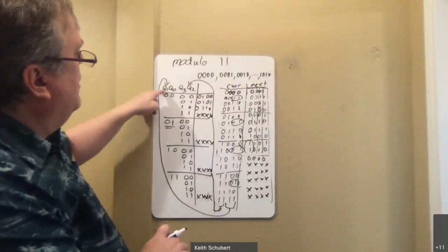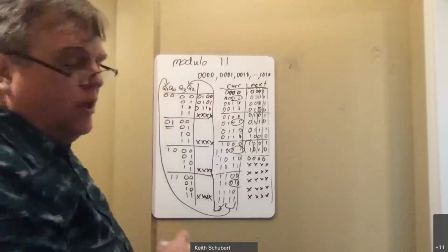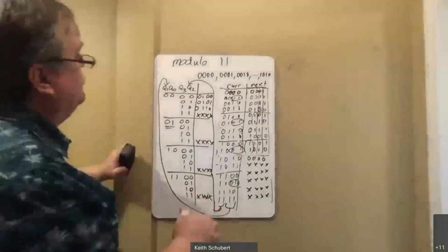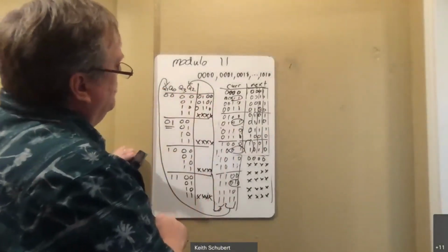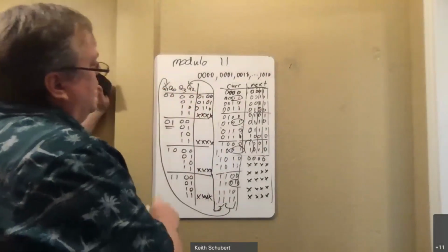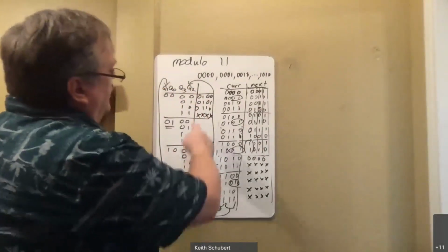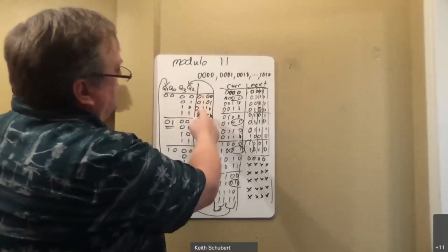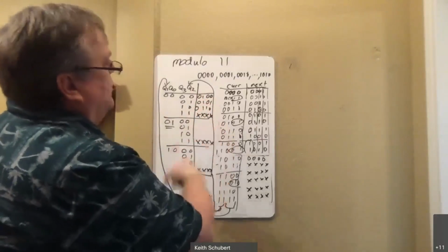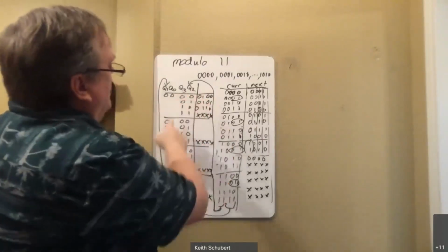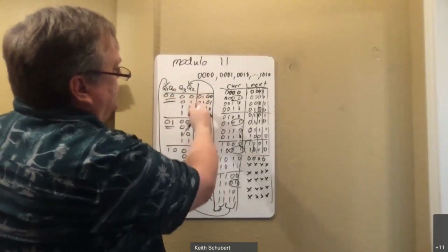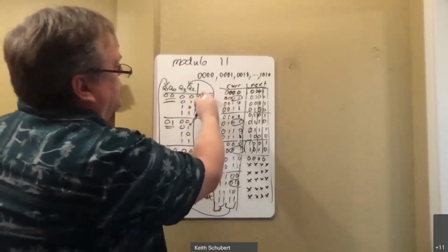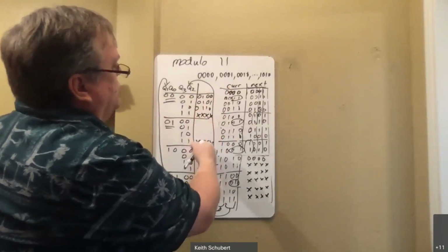Right? You've now used Q1 and Q0 for your 4-bit muxes as the addressing. Then you've got Q3 and Q2. Right? And when you look at the patterns in here, 0, 0, 0, something. What could I put into the mux at input 0 that would give me all zeros? And then whatever I want to choose. All ones and what I want to choose.